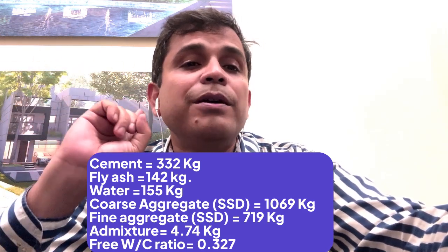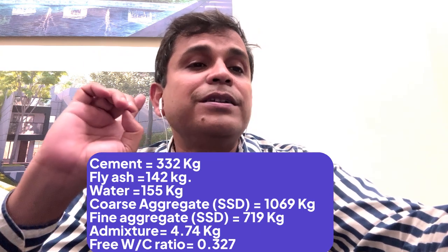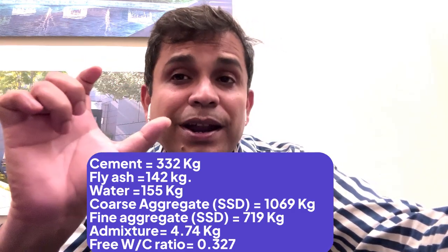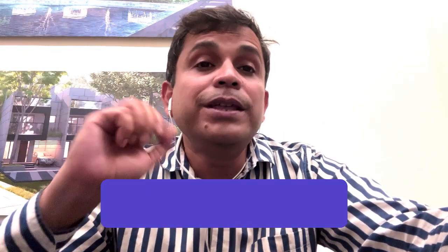Now, what is my fine aggregate quantity? That is 719. If this 719 is not only sand but sand plus moisture, then what is the percentage of moisture? That is 4%. So what will be the sand quantity to take to get the 719 kgs of fine aggregate? How much will be the total quantity?